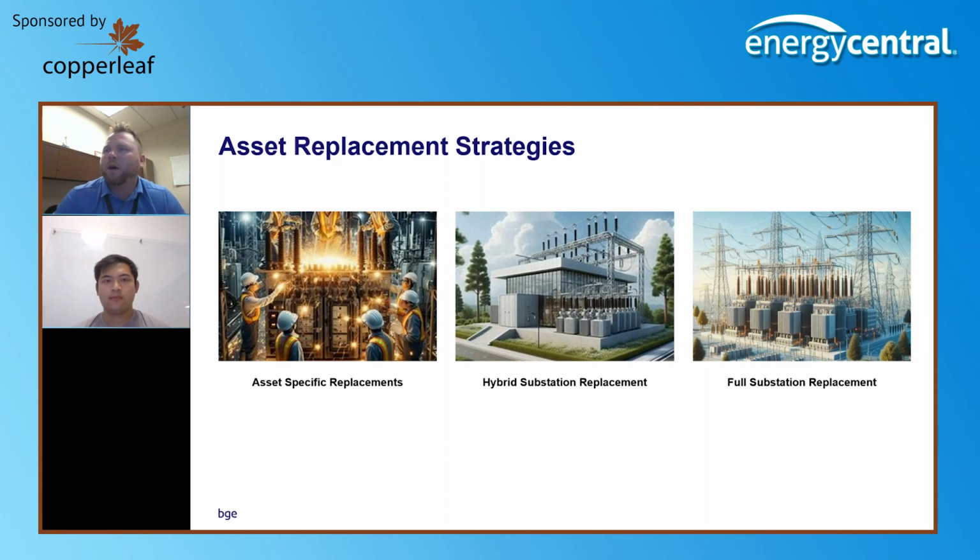Another interesting one that we're exploring is a few substations where we have room in an end of a breaker and a half scheme to build out a brand new bay. And so we have 3 OCBs in an existing bay, building out the new bay with vacuum breakers, having all new switches, control cable, new cable out to the feeders. Because it's not in an existing bay, it's like a greenfield site in a brownfield area. It's allowing us to work outside of our typical outage season and drive efficiencies from that perspective.